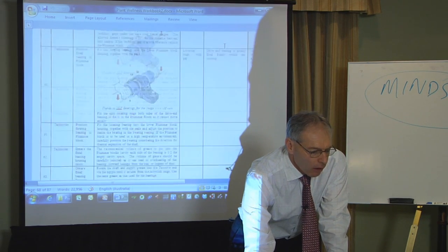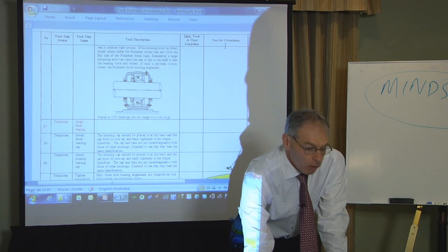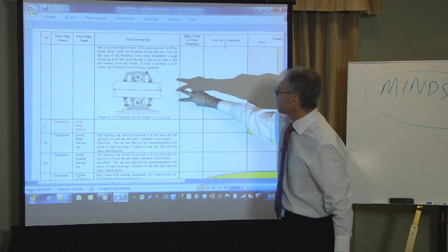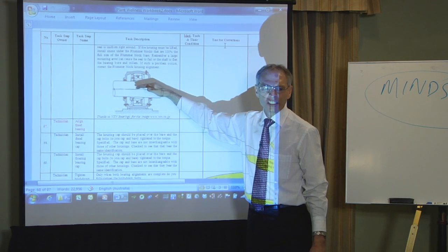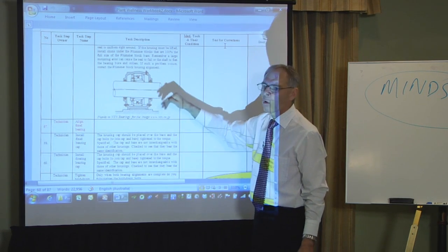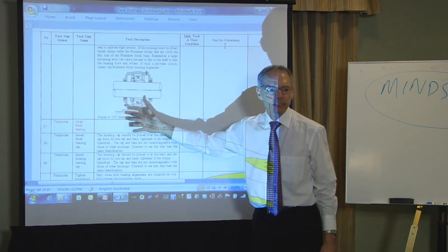We go on down. Oh, look, I've got to assemble it properly, install it properly. I'll get the alignment of the shaft right so I don't damage the seals. Because if those seals are damaged, all my rubbish goes in there and I won't get 5 or 10 years trouble-free. It'll get full of water and it'll be down again in 3 months.